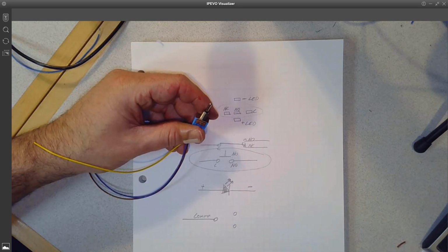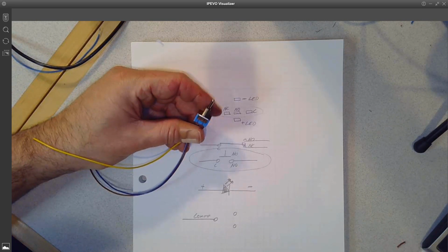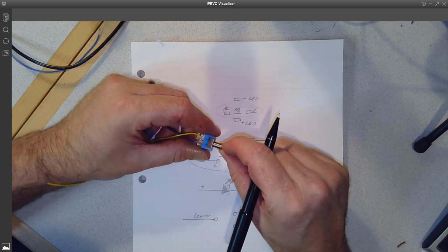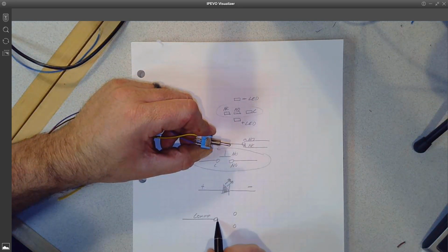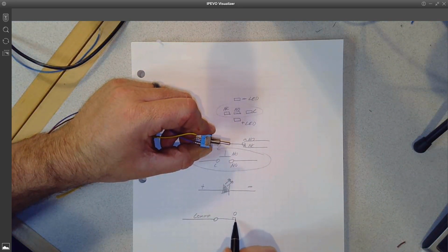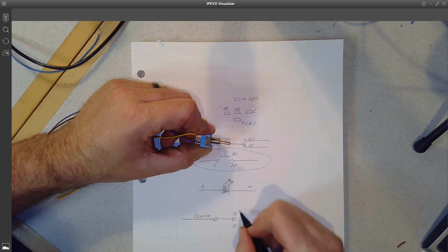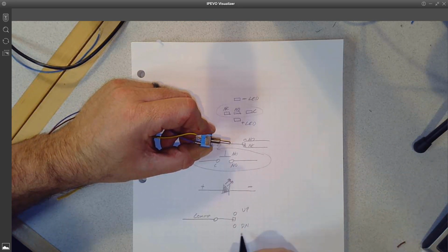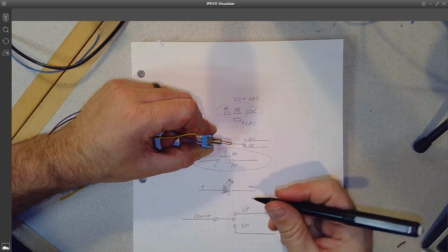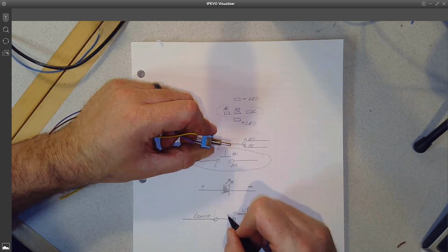And neither one is considered normally open or normally closed here because we have a middle off position. So now we're just going to have a terminal, and this one you could label up and this one down, and then those could go to 2 different inputs on your PLC. So there's a representation we can use for the toggle switch.